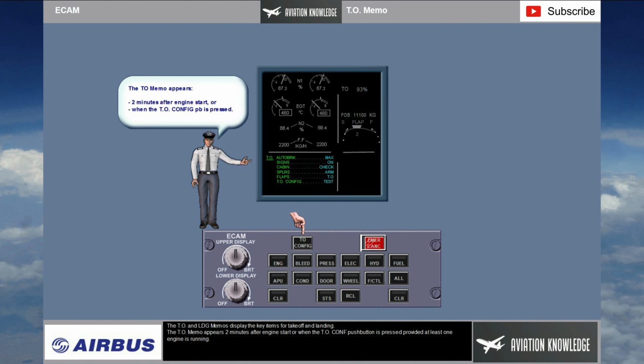The takeoff and landing memos display the key items for takeoff and landing. The takeoff memo appears 2 minutes after engine start or when the takeoff config push button is pressed, provided at least one engine is running.